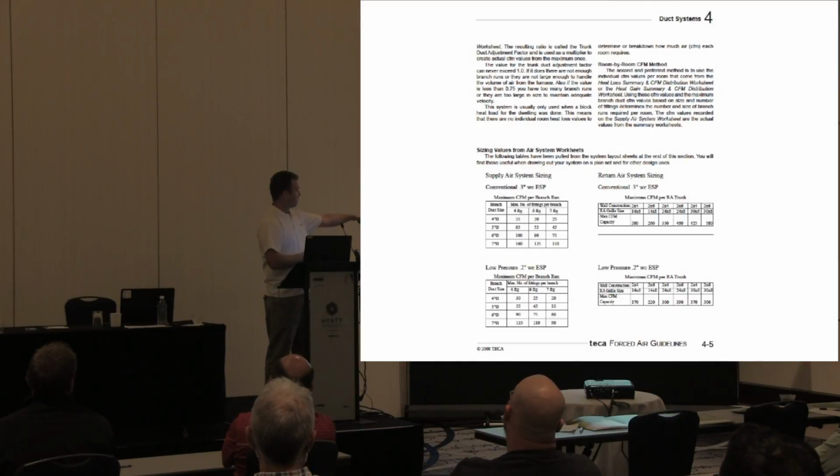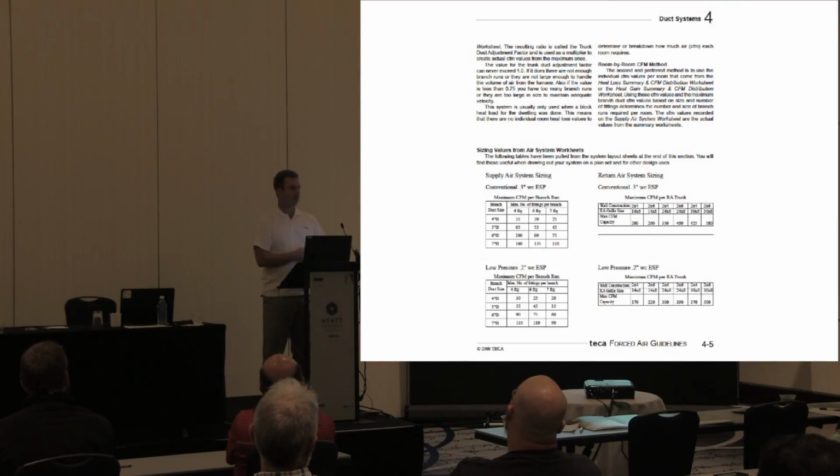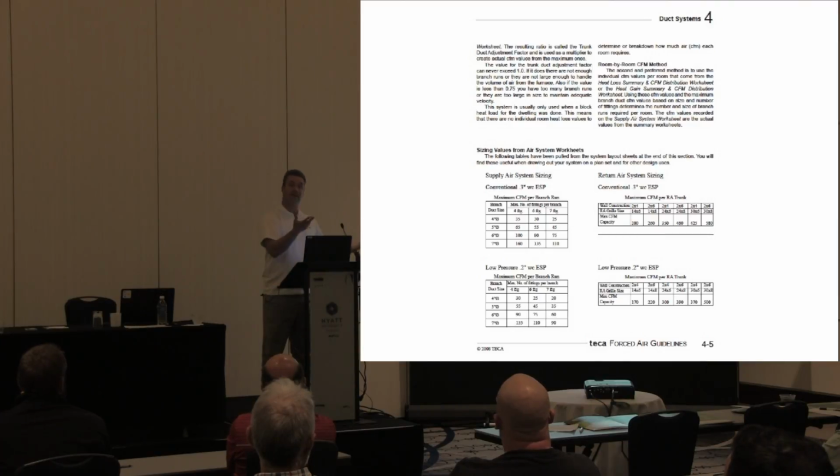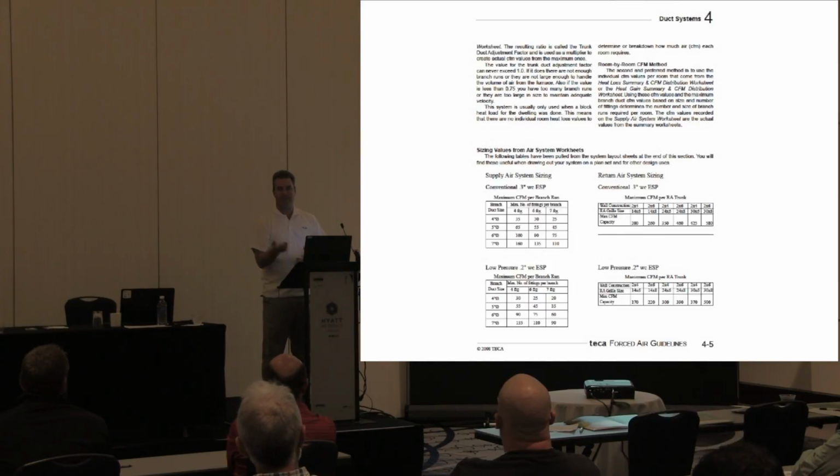Basically it tells us that on an easy short run, a 4-inch vent will give us 35 CFM, but if we had a 7-fitting run and have to go all the way to the top floor, we're probably looking at only 25. Percentage-wise it's about the same for a 5 or 6-inch, which would be more common. A 6-inch is 100 CFM on a short run, like a basement or main floor, but we're down to 75 CFM once we get to the top floor. So if we need 100 CFM on the top floor, running a 6-inch is great, but it's not going to deliver 100 CFM if we have that many fittings. You're going to have to upsize it or put 2 vents up there instead, or something else will have to be done.